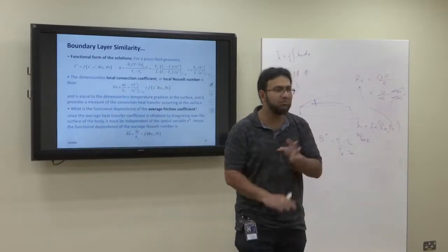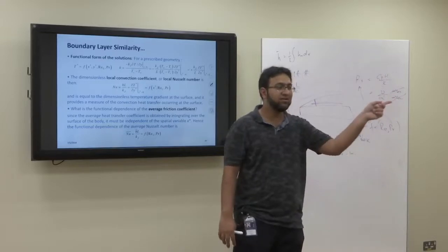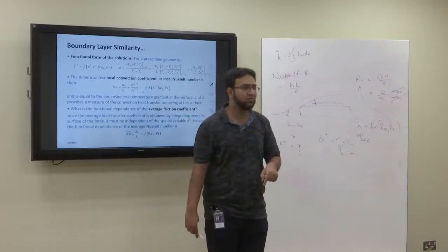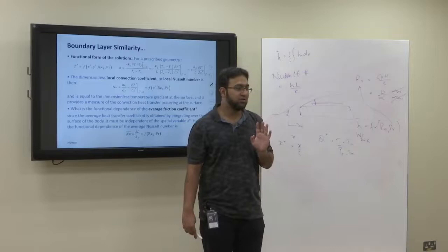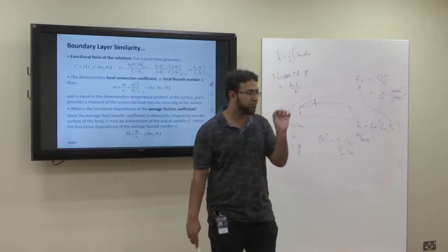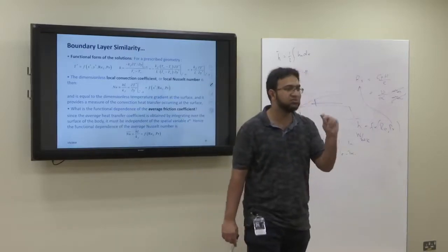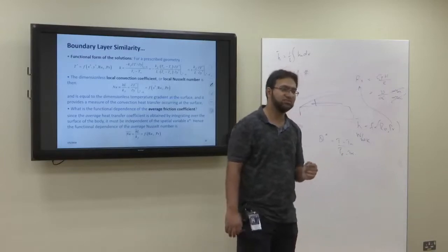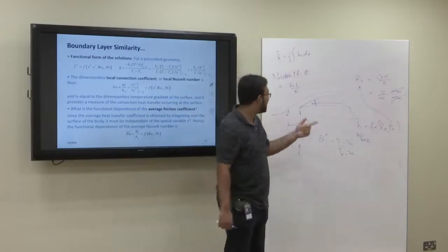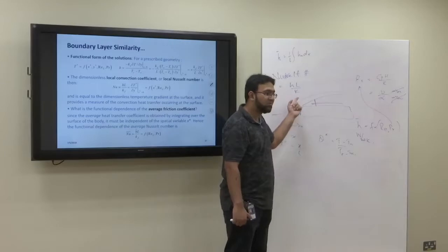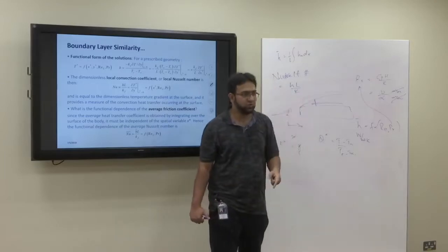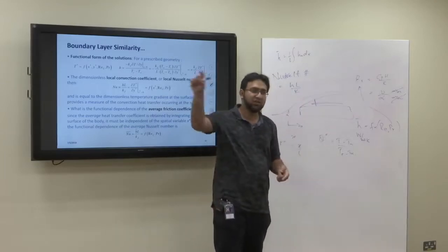In case of Biot number, k is of the solid. In case of Nusselt number, k is of the liquid. Now this is a very small difference, but this is the area where students make a lot of mistakes. They forget that k for the Nusselt number was not for the solid, it was for the liquid, and they put the k value of the solid.